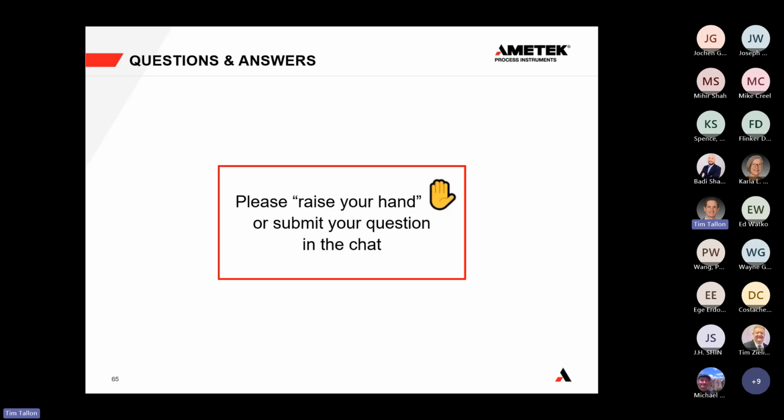The hydrocarbons measurement can measure light hydrocarbons like methane, like ethane, like propane, in some cases butane. As it gets bigger and more complicated, to things like coal or like biomass or bunker, a hydrocarbons detector would not measure those particulates like coal, or those particulates like biomass. Those are all particulate heavy, and so the hydrocarbon detector is more designed for those light hydrocarbon fuels that we see at the burner, or as a supplement.